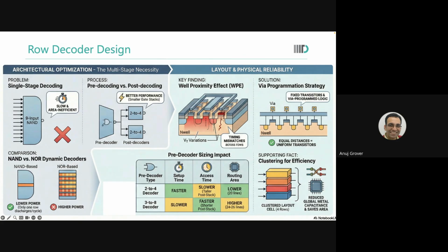Setup time is always like a relay race. The system is ready and the clock comes, you should just simply be able to run. To be able to do that, the system should be ready. And that means that the address should be stable at that particular transfer point. That is what your setup time is. The transfer point is far inside the memory. It means someone has to walk a much longer distance to be able to be ready and accept the baton.